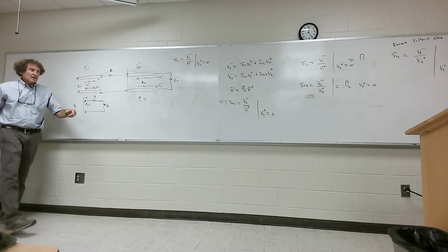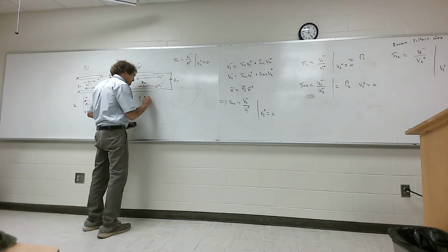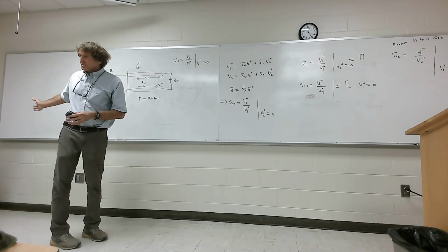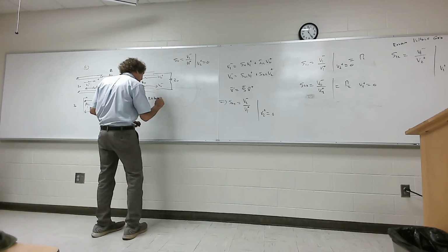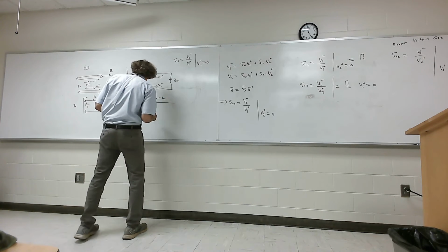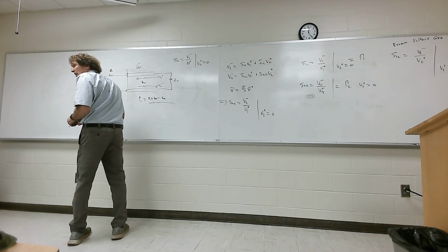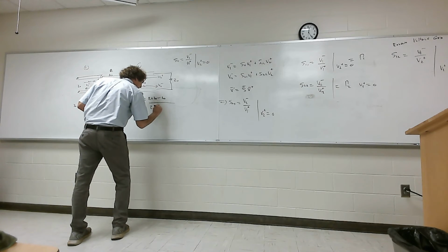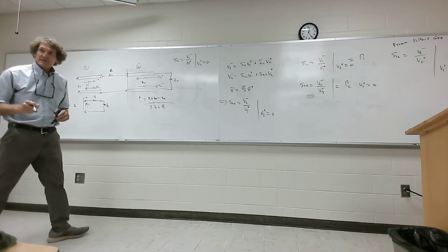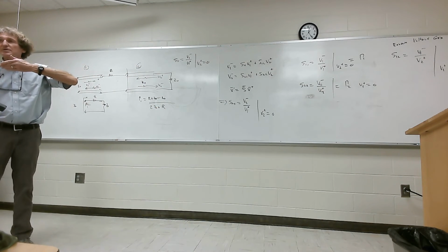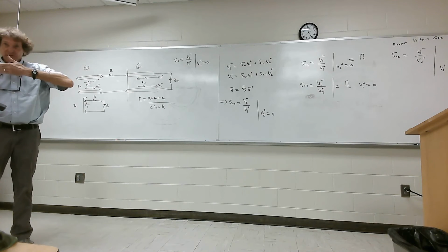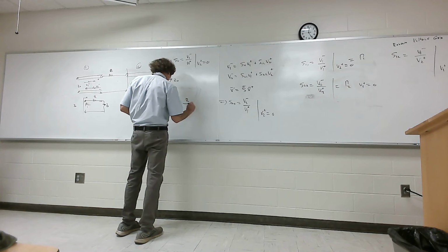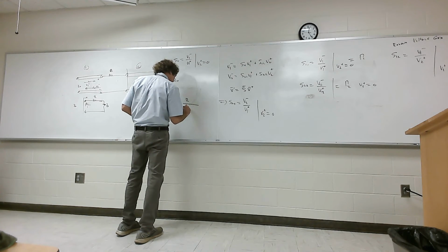Y'all see that? So it's R plus Z0 minus the impedance you came from, which was Z0. This is characteristic impedance. Y'all see that? Minus Z0, right? Over the sum of what? Of both. Y'all agree? So that would be 2Z0 plus R. Y'all agree with that, class? Impedance you're going into minus the impedance you came from over the sum of the two. And what's that going to be? That's just R, right, over 2Z0 plus R.